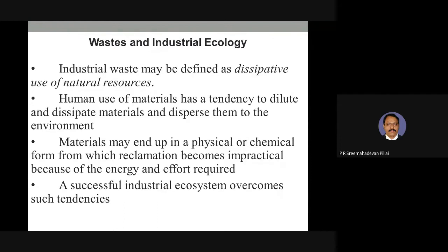Textile waste is mostly having colored dyes. These dyes will not disintegrate by itself. So what you have to do is you have to separate it, you have to dilute it, and the diluted sludge you have to send out to the field, maybe to the paddy field, etc. In Kannur area, this is a heavy environmental issue. So many textile firms are there. Luckily in Palakkad, only 2-3 textile divisions are there. But even there, the output water which is coming out of the industry is having colored dyes.